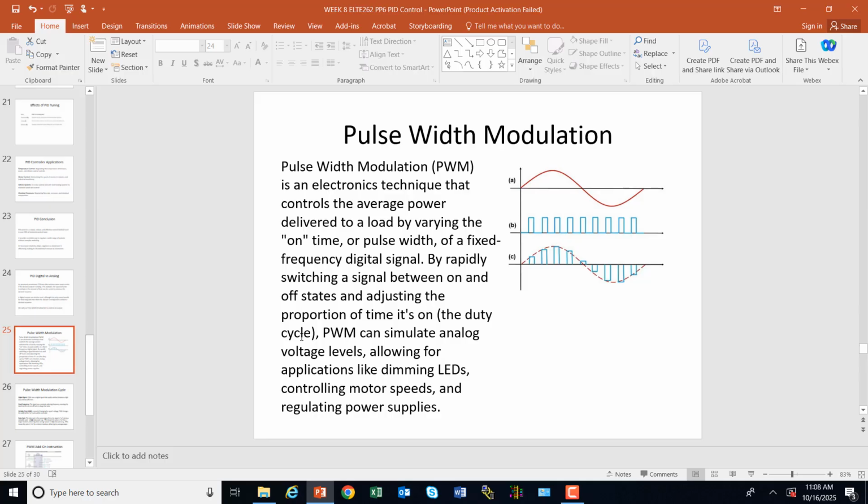And we've talked about pulse width modulation, shown right here, when we talked about variable frequency drives to change the speed of an AC motor. That's how a variable frequency drive does it. It pulses voltage for a longer or shorter amount of time to approximate the sine wave.